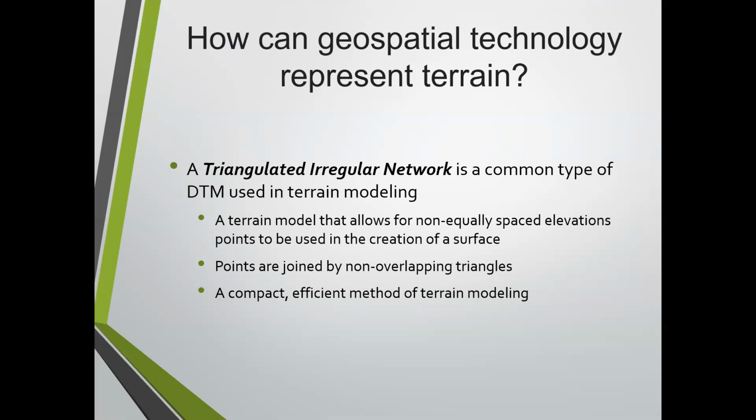And what those break lines do is they give it complete guidance. And if a triangle face shoots across a creek, what you're basically doing is putting a dam in there where there really isn't one. So that's why those kind of things are important. And especially if you have a lot of man-made features like curbs and centers of roads and those kind of things, you obviously need that. But yeah, I agree.